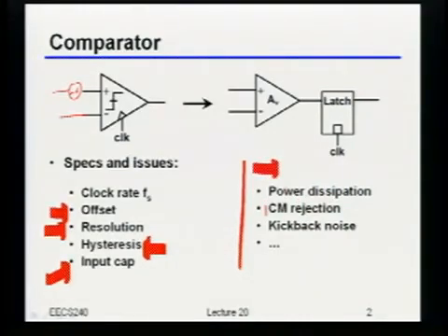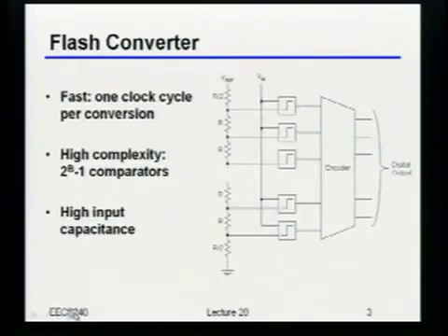And as we'll see a little bit later on, comparators have this very nice property that they like to do what's called kickback on their inputs. In other words, if you had a nice clean 10 or 1 millivolt signal over there, well, you've got a volt of signal over here, or 2 volts, or however much your power supply is. That means if there's any coupling from here back onto there, you could very easily screw up your nice clean analog input signal.